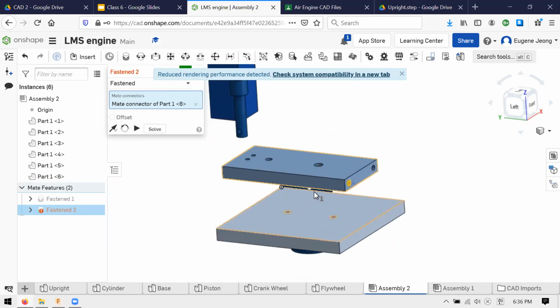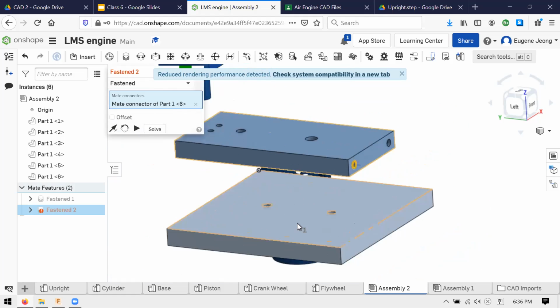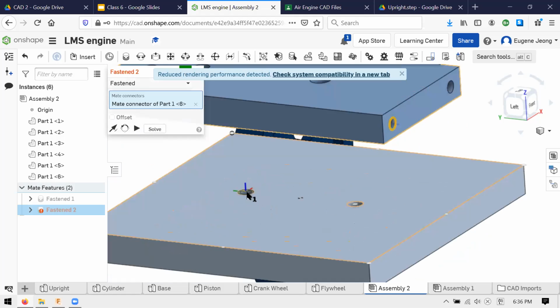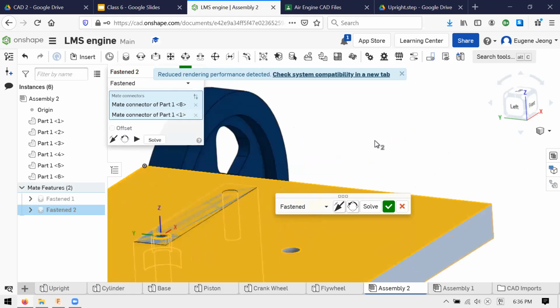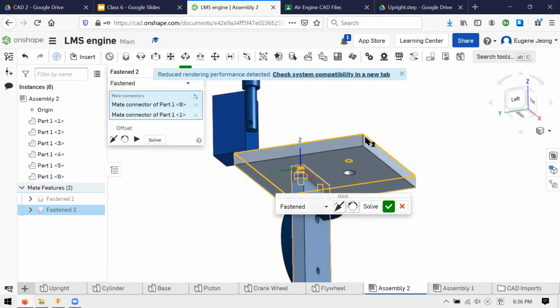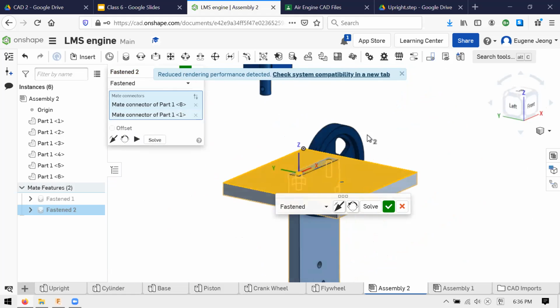If you wanted to, you could go, for example, to McMaster and download the CAD file for the screws, as we talked about how to do 2 weeks ago. And just like we're doing right now with the bigger parts, we can mate the hardware in as well. But like Peyton said, we're going to do a fasten. You can pick one of the circular outlines and another circular outline. And there's a good chance you might get something like this, which is clearly not what we want.